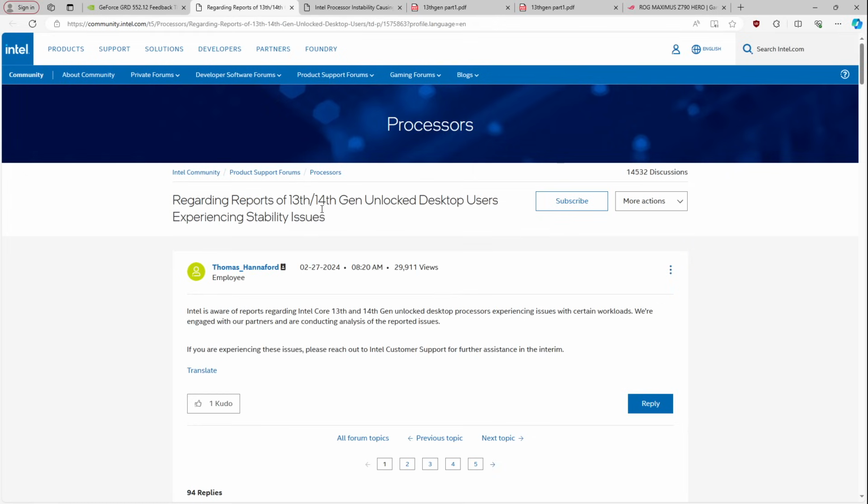So that's probably not safe for the CPU, but in the short term, you can at least get it stable. With the 13th gen, 14th gen CPUs at 100 degrees Celsius, if the CPU is crashing, it just needs more voltage, right? Like, that's it. If you don't really care about anything else and you just want to fix the crashing problem, you can literally just raise the core voltage and that will eventually stop the CPU from crashing.